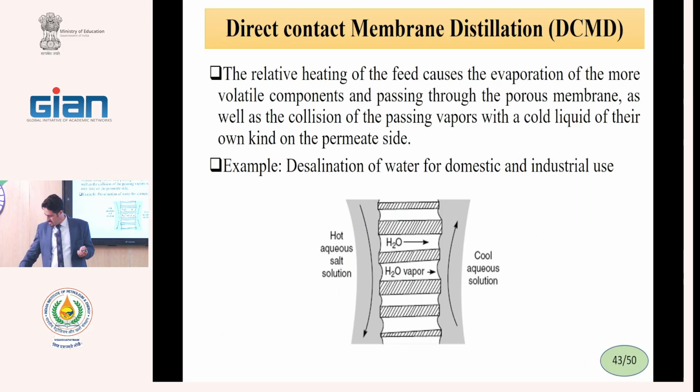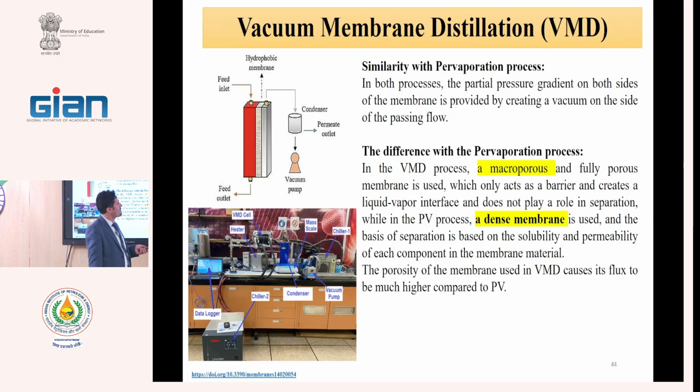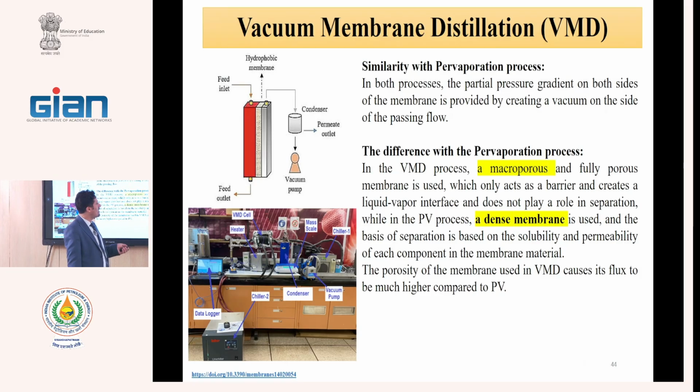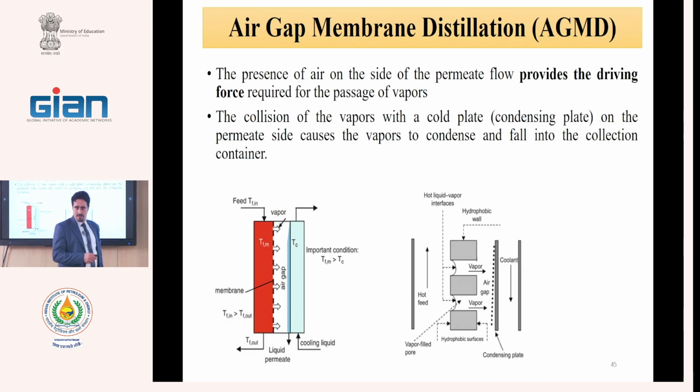I discussed these slides. This is the lab scale vacuum membrane distillation. I said that we do not like the pores to be filled with the liquid, and the pore size and the hydrophobicity of the membrane are very important.